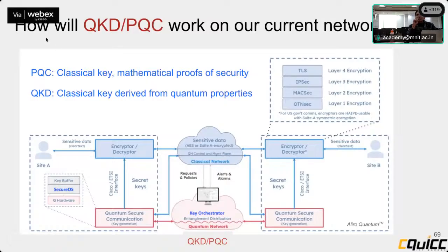We missed one question, which is any difference between legacy fiber link and quantum fiber link from end-to-end power budget link? No, I don't think there is any difference in the power budgeting. It's just that the power budgeting is always done from transmit to receive, and the receivers in a classical link are not as sensitive, and the power is very high. In the quantum links, the transmitted power is very low. It is the energy of a single photon, and the receiver has to be that much more sensitive.